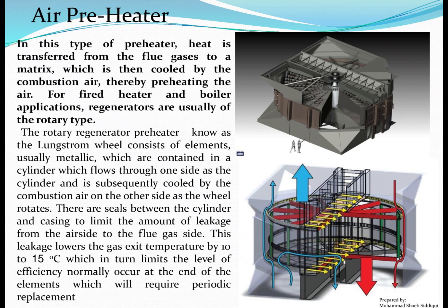Regenerative air preheater. In this type of preheater, heat is transferred from the flue gases to a matrix, which is then cooled by the combustion air, thereby preheating the air. For fired heater and boiler applications, regenerators are usually of the rotary type.